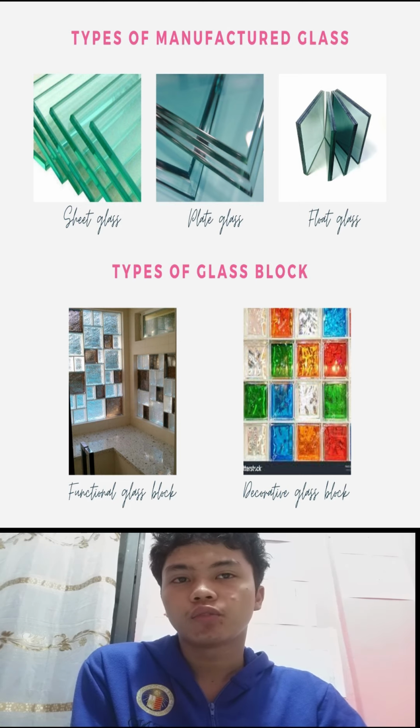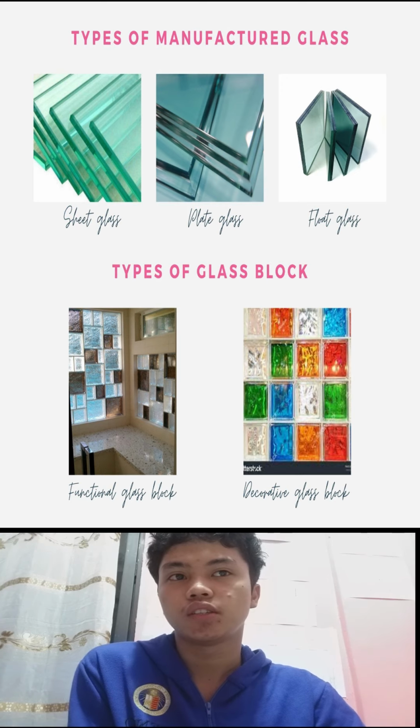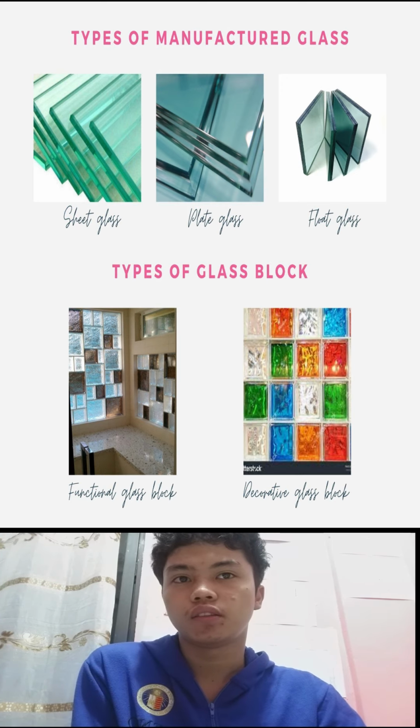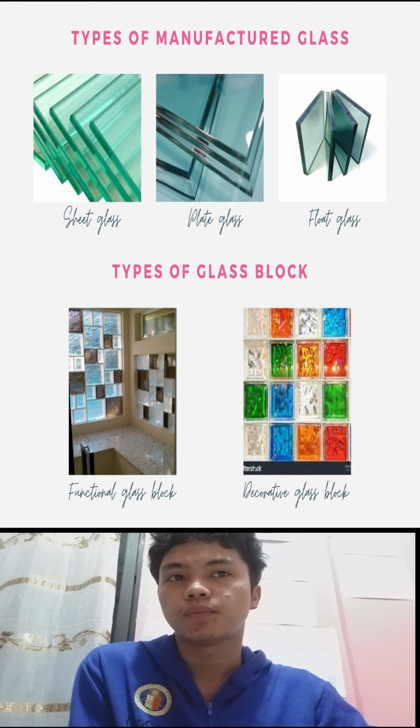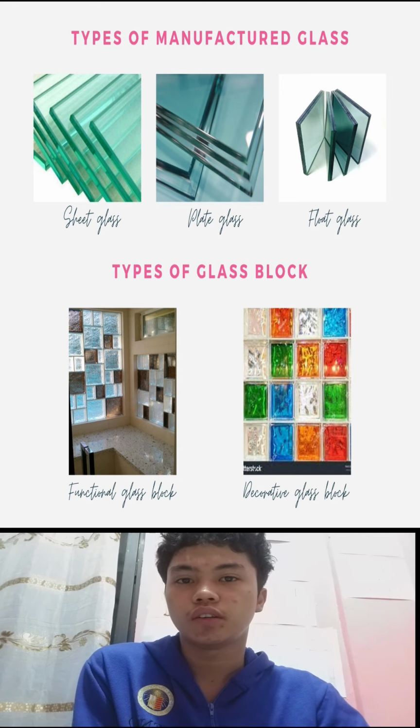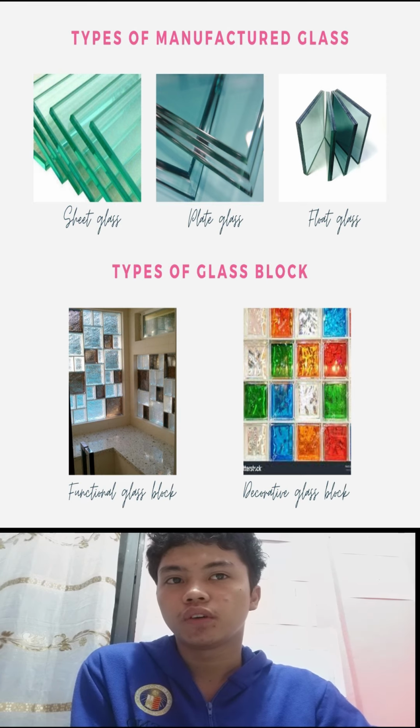Plate glass. A high quality sheet of the same chemical composition as sheet glass. Plate glass can be produced in thicknesses of from 1/8 inches to 1 and 1/4 inches. Although the specialty glasses are usually cast rather than made by the continuous flow processes. This is special because both surfaces of the 100 inches wide ribbon of glass are simultaneously ground by a twin grinder unit. Then when cut, it is polished with a jeweler's rouge to give undistorted clear vision and reflection.